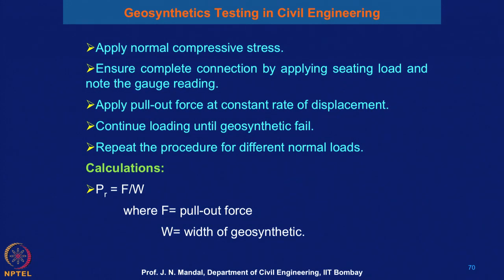So, then you can apply this normal compressive stress. Ensure complete connection by applying the seating load and note the gauge reading. Apply the pull out force at a constant rate of displacement and continue loading until the geosynthetics fail. Repeat the procedure for different normal loads.